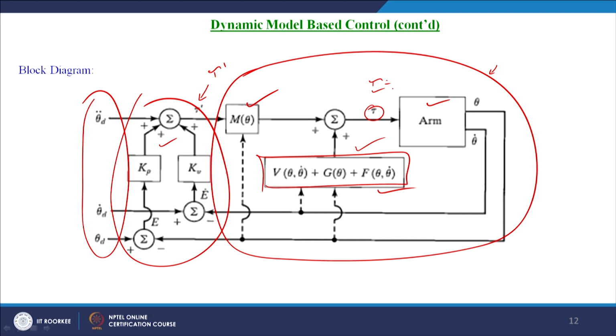This is the control part, and giving the joint torque to the robotic arm, how do we get the joint angle and joint velocity? Because we need to have the error coming out from the servo law, which will be happening because of the discrepancy between the desired trajectory and the actual trajectory. So, we need to know the actual trajectory.